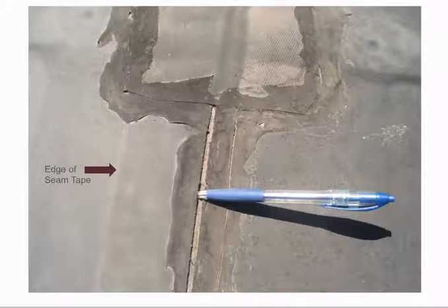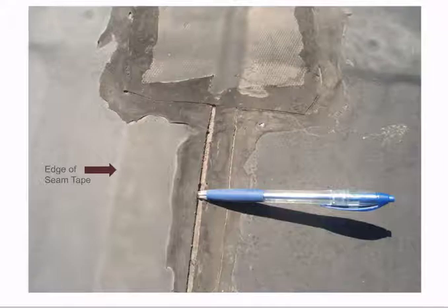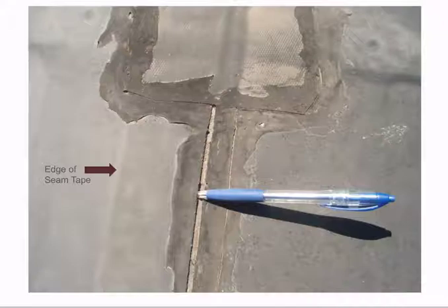Yep. Okay. And then here it looks like we've got a common-looking EPDM system. What's going on here? What we have here is the membrane shrinkage over the years. It will shrink a little bit, and then it'll expose. You can see that crack where the pen is. That's just where the sealant was applied, and it's actually pulled away, and the pen is actually stuck into a little tiny fish mouth. It can create a problem downstream, but as of right now, that's not a leak.